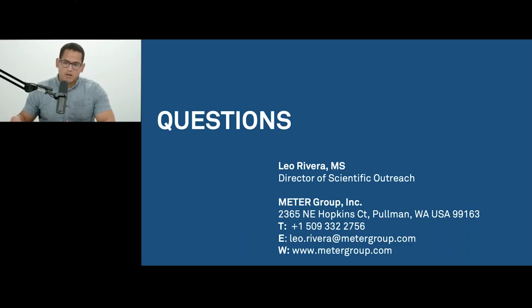But yes, you can. And typically what you're going to do in your models is take the hydraulic conductivity value, that final K value, and input that into your models. Now, if you also need unsaturated hydraulic conductivity for your model, then you might have to look at incorporating some other tools like a tension infiltrometer to get that unsaturated K value. But it depends on what parameters you're inputting into your model.